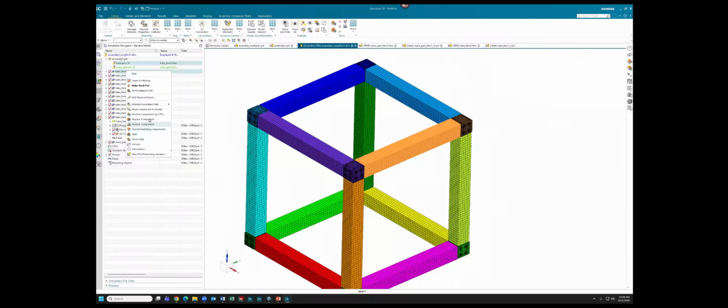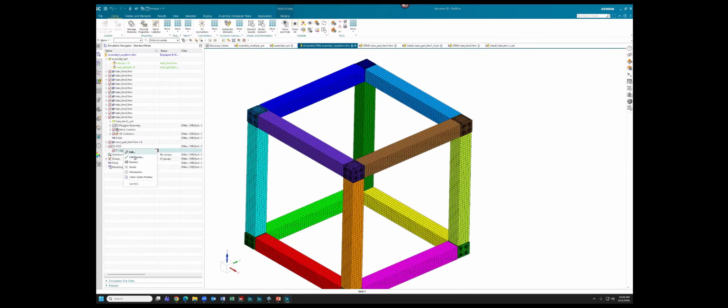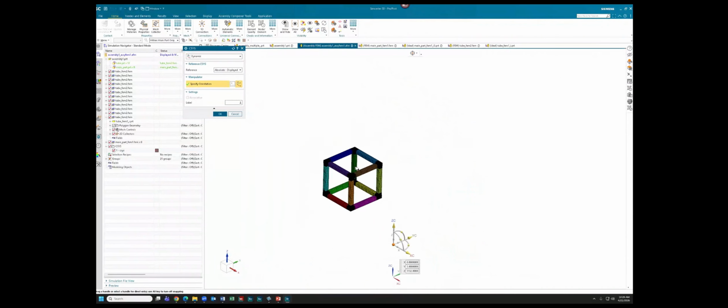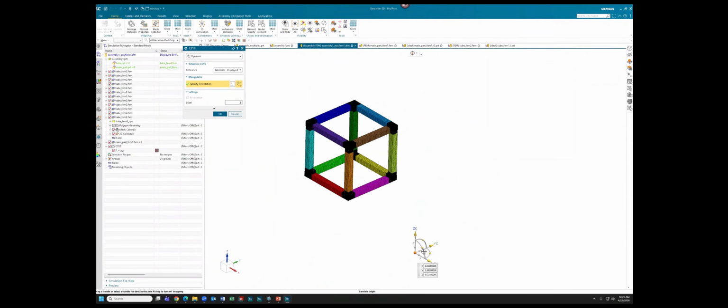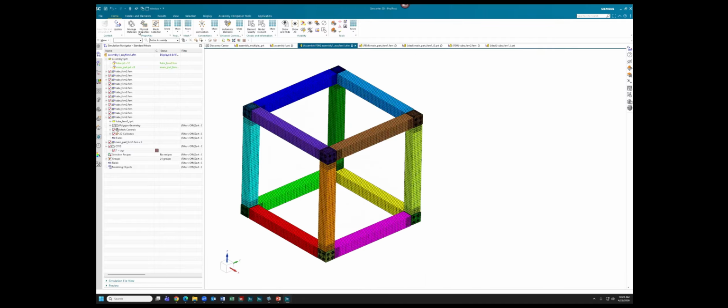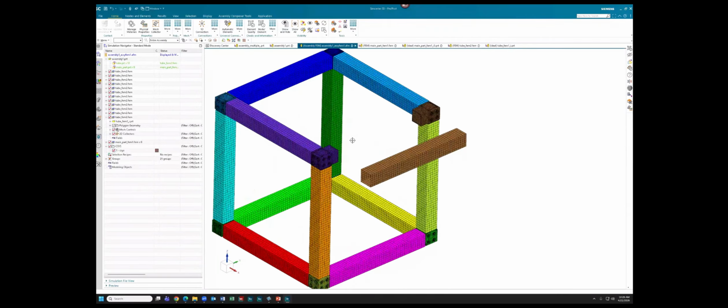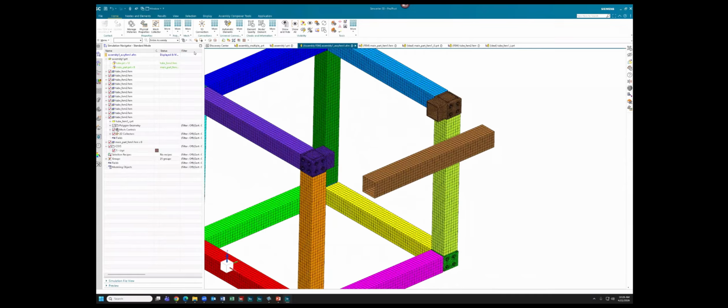You could do things like maybe you want to reposition one of these FEMs manually with a coordinate system within the AFEM. You can do things like that. Again, you're essentially breaking your mapping of your assembly FEM when you do things like this, but you do still have the option to do so and it can potentially be useful for, once again, quick iterations on design or changes.